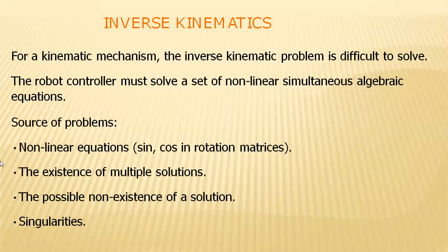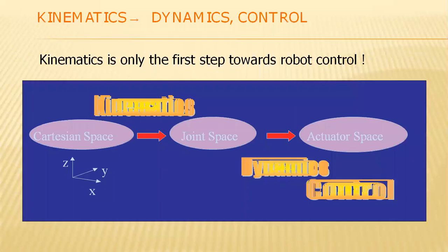There will be sources of these problems, because the nonlinear equations will be simultaneously generated, leading to theta deflections in its coordinate frames, towards the sine and cosine in its rotational matrices, and the existence of multiple solutions, the possible non-existence of a solution, and singularities will be clearly found in the case of inverse kinematics.